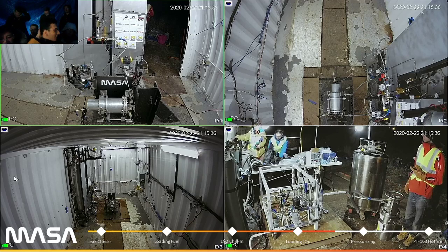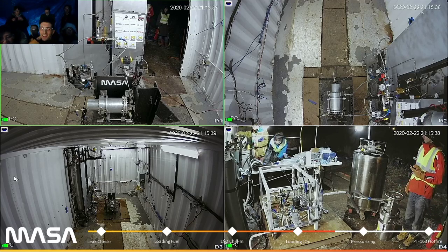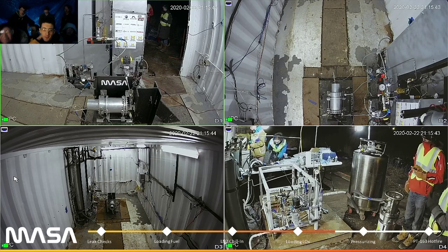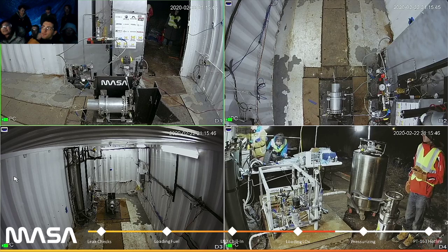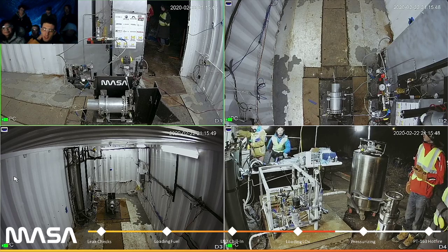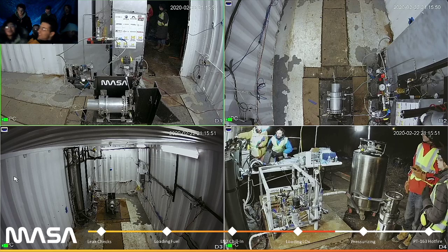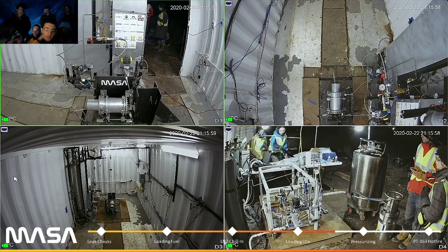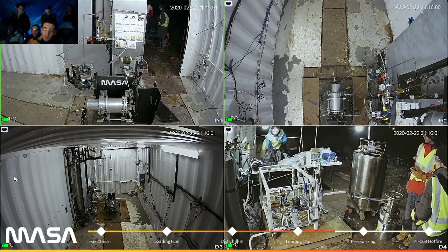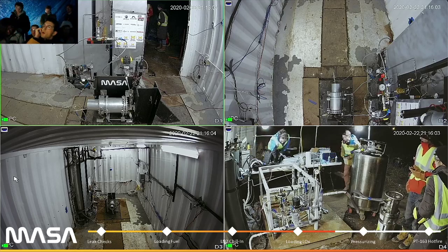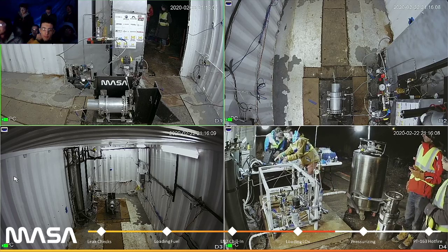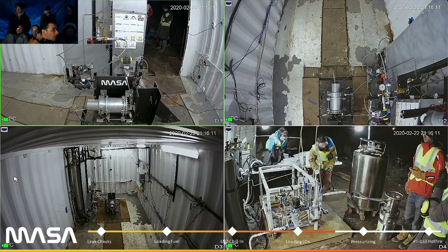So in-house valves are definitely possible. They're difficult, but they're kind of necessary since off-the-shelf solutions don't really exist, and unless you want a massive, heavy pneumatic actuator, then you kind of need to make your own. Also, whenever it breaks, you don't know what went wrong because you didn't make it. And what type of valves are they? They're poppet style valves with a kind of piston aspect, so that you can pressurize one side of the valve and it pushes the poppet the other direction to open flow.